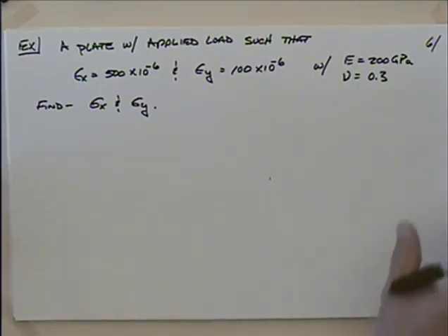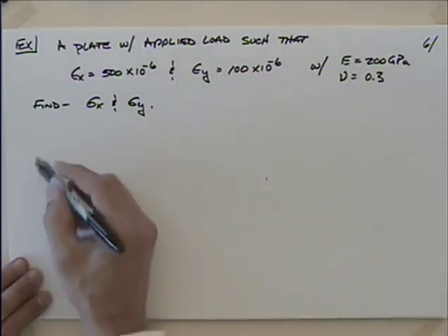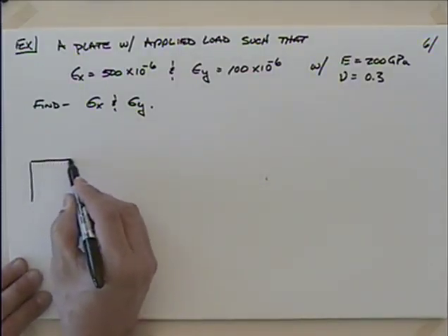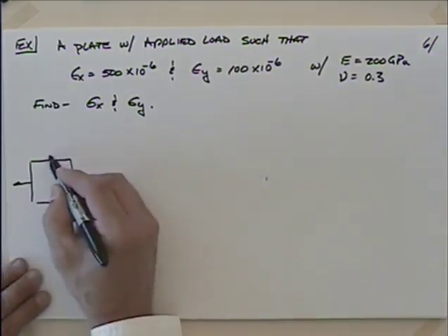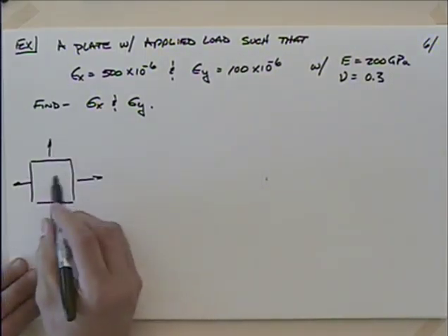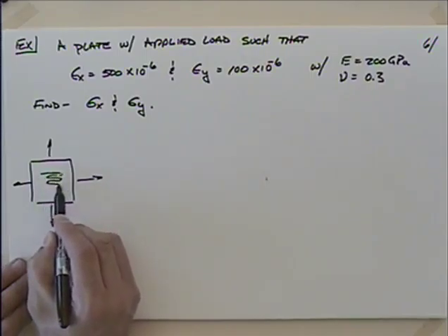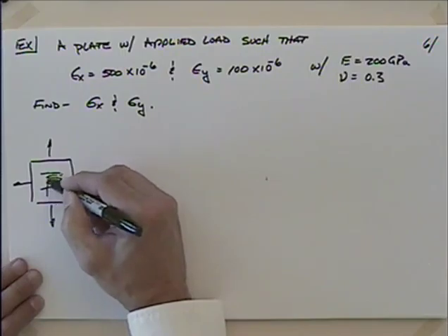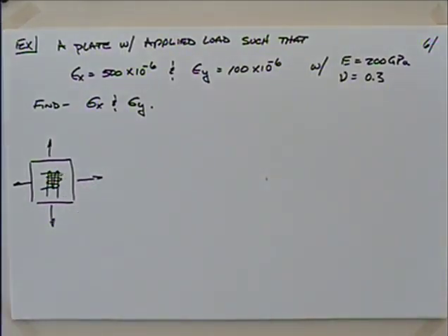We can use a strain gauge, and I've talked about this in the past, but a strain gauge might look like this if we have something that has a couple of loads on it. We could put a couple of strain gauges here. We just put this very thin wire and we would bond this. And we could do it a couple different ways like this, so we could get the stresses in one direction and the other. Usually you don't do it just at right angles. You might do it in an equilateral triangle or something. You got some homework problems that'll help you with that.